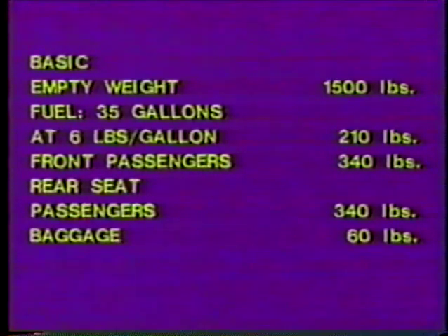Always use actual weights of people and baggage. Although the airlines can safely use a standard weight of 170 pounds per passenger, even one person's weight difference from standard affects the general aviation airplane's performance.